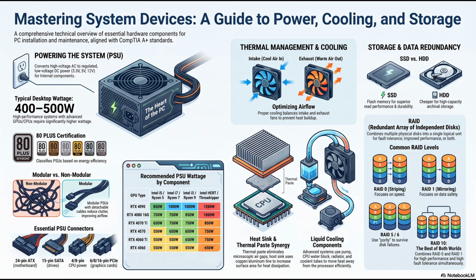There's a small notch cut into the bottom edge of the RAM stick where the gold connector pins are. The position of that notch moves slightly with every iteration. It's a physical, idiot-proof failsafe. It is absolutely necessary, because a DDR4 module might require 1.2 volts to operate, while a DDR3 module required 1.5 volts. If you could physically force an older stick into a newer motherboard, the voltage mismatch would immediately permanently fry the memory controller. The physical notch prevents catastrophic user error.